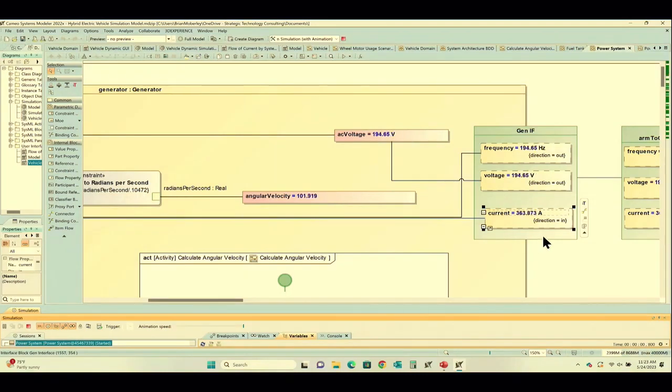What you'll notice is that current is actually coming into the generator because we want to see how that affects the generator. And if you've ever used a skill saw with a generator possibly, or ever ran anything off of a small generator, what you'll notice is anytime you draw current, you'll hear those RPMs dip down. You hear it go, right? And that is actually what we can show it do in this model. And it's because it actually puts a counter torque on the generator. And you can model exactly how much counter torque that is using a few equations.